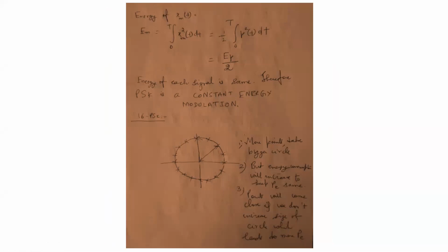If you want to send 0, 0, 0, 0, 4 zeros, then you will have to pick this signal and transmit it through the channel with a phase difference. Here the phase difference for this signal is 0. And at the receiver, when this signal is received, since the phase difference is 0, the receiver will find out that 0, 0, 0, 0 was transmitted. In the same way, other signals are transmitted corresponding to the combination of bits they are used to represent.